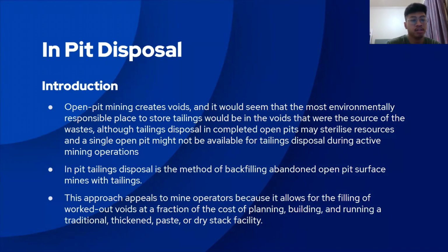Now is the in-pit disposal. Open pit mining creates voids, and it would seem that the most environmentally responsible place to store tailings would be in the voids that were the source of the waste. Although tailings disposal in a complete open pit may sterilize resource, and a single open pit might not be available for tailings disposal during active mining operation. In-pit tailings disposal is the method of backfilling abandoned open pit surface mines with tailings.